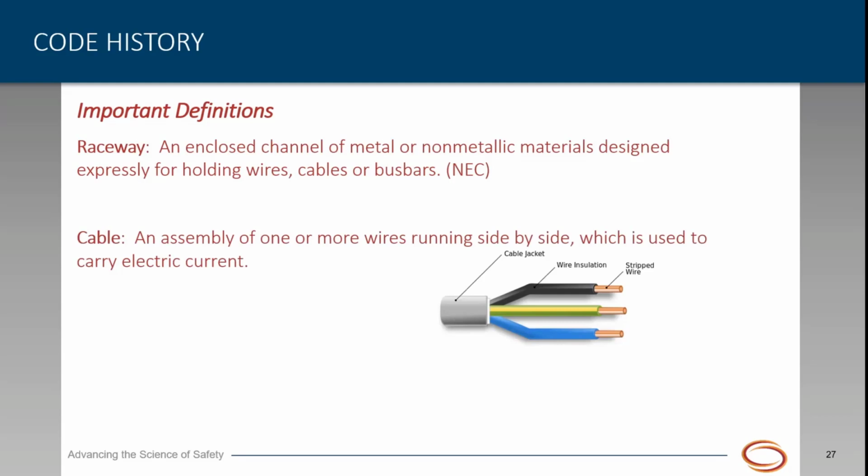Now, a cable can include 2 or more conductors or wires, and it can include paired or multi-conductor cables, some with twisted or shielded components, coaxial, optical fiber, all kinds of options for cable. And the cable jacket is simply an outer protective jacket. It's just used to protect the conductors inside. It can be made of various materials, some with temperature ratings, some with chemical protection or other. Circuit integrity cable, CI cable, is an example of using a different outer protective jacket as a way to make the cable survivable. But an average everyday cable jacket does not make it survivable.